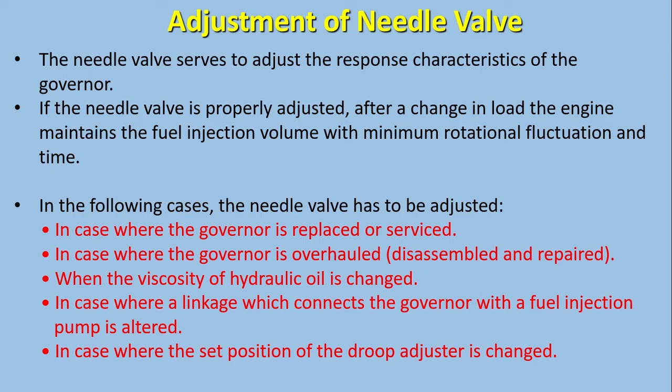If we open the needle valve more, at that time the governor will be too sensitive, too responsive to changes in load. So at that time hunting will occur. So that's why adjusting this needle valve is very important for the stable operation of the governor.